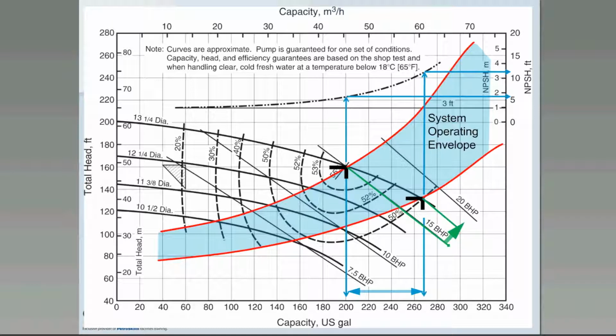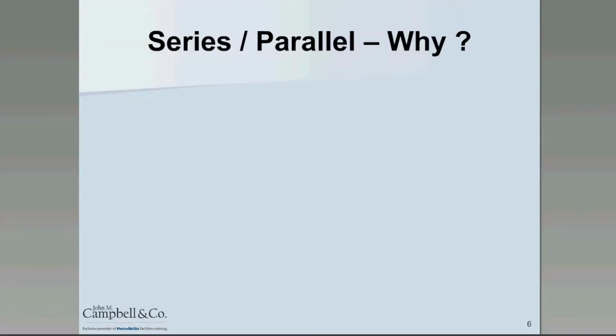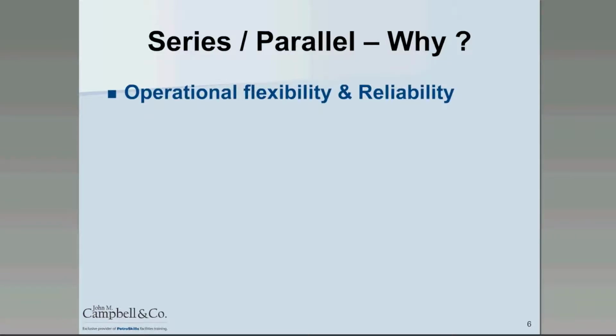And here's that discussion on power that I mentioned a second ago. So talking more about series and parallel pumps now, trying to understand why we have them is important. And some of the various reasons that we may consider having pumps in series and parallel: operating flexibility, allowing an operator to have multiple units installed in parallel where they can take a unit offline to be able to do maintenance and so forth, or perhaps they've got different performance requirements in a pipeline and they can put more pumps on to be able to move more or less fluid, turn down or increase production.